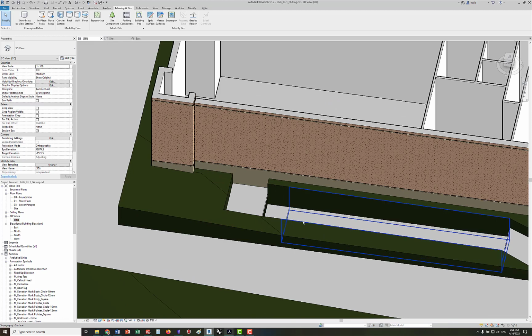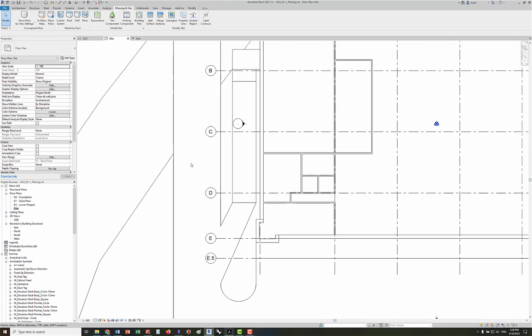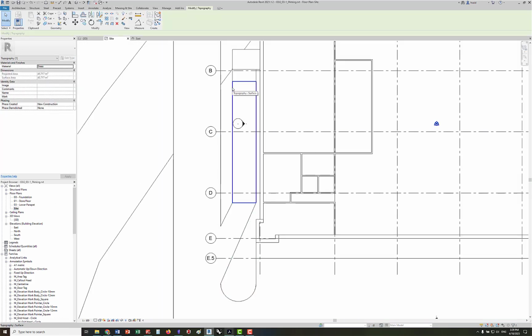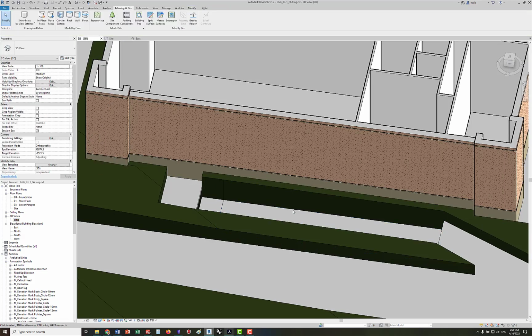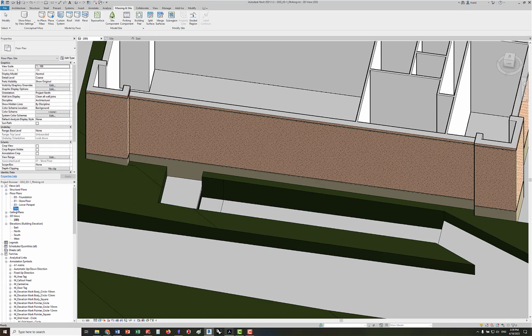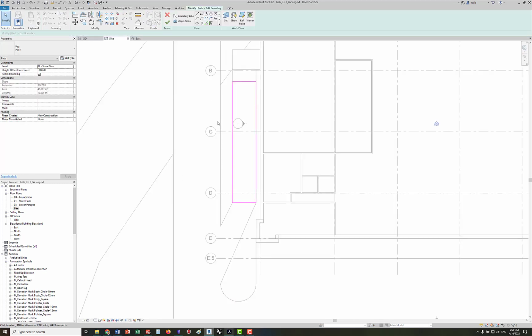So I need to have this side lifted up to here, and this side here will be the same as this, as it is now. So going back to site, I have to go back to 3D and pick this building pad, going to site, and then edit boundary. And then I will draw a slope arrow. So I'll draw from here to here, from the edge to the edge. And now I will control the elevation of the edge or the tail to the other edge, which is the head of the slope arrow. So this edge has to be the same level as the parking lot.